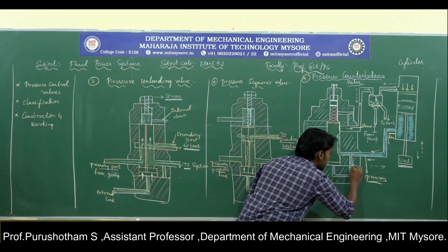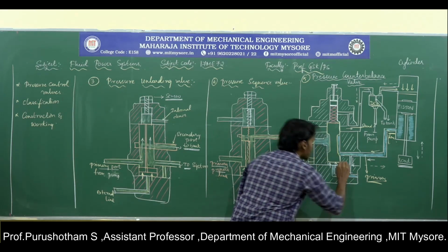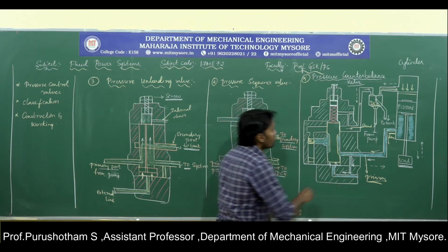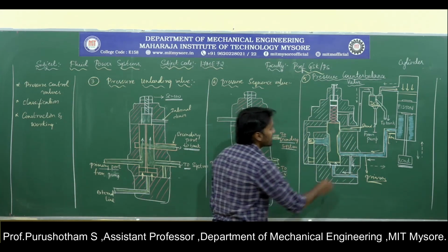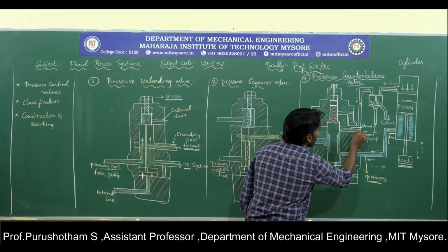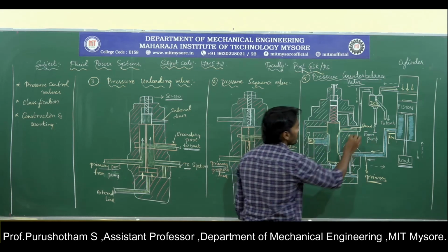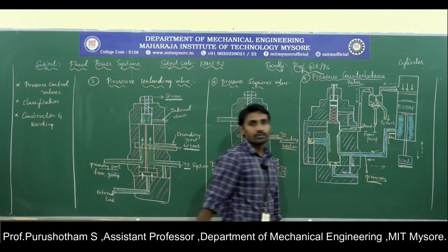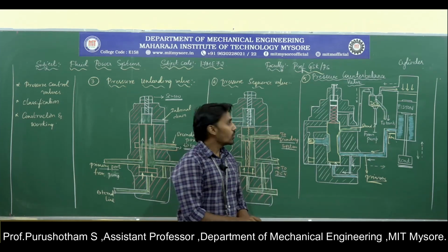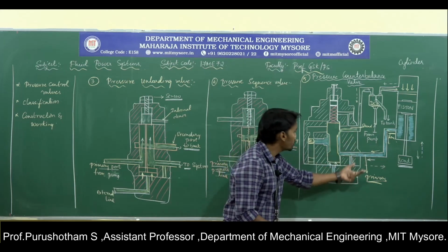The fluid in the pilot line moves the piston upwards, which creates a passage between the spool and the secondary port. Then the fluid enters the direction control valve and goes to the tank. This is about lowering the load, so this will be a smooth operation.